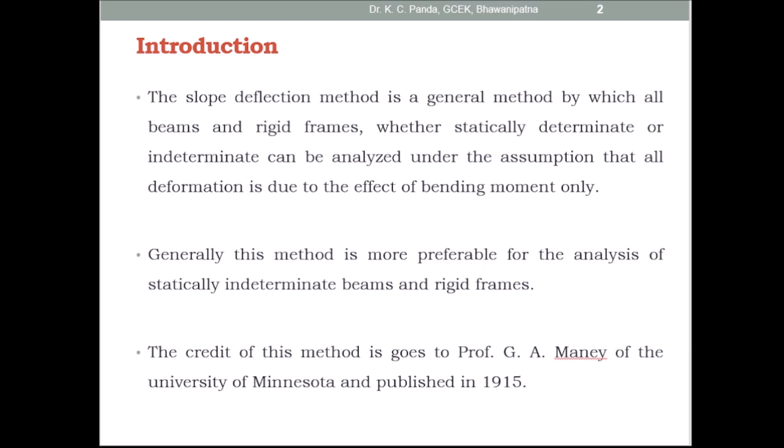First, coming to the introduction, what is the slope deflection method? The slope deflection method is a general method by which all beams and rigid frames, whether statically determinate or indeterminate, can be analyzed under the assumption that all deformation is due to the effect of bending moment only. Generally, this method is more preferable for the analysis of statically indeterminate beams and rigid frames.